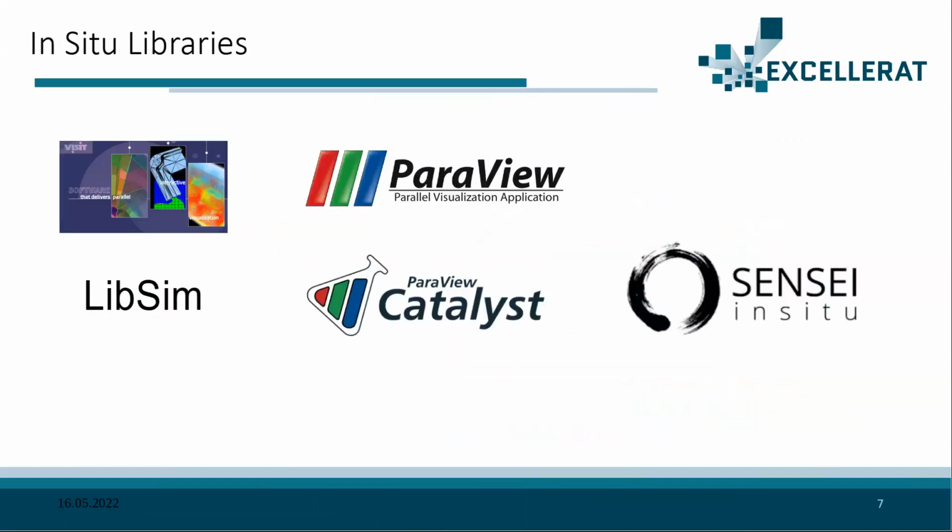And to do this, there are a couple of existing approaches. So as I mentioned, NEC already had the LibSim interface, which is a proprietary interface for the VisIt post-processing software. And the same applies to ParaView, another common post-processing software, which has its own proprietary interface. And we could have done something similar for Vistle and NEC to implement an interface, especially for Vistle in NEC. But we didn't want to go this route because it's not really scalable. It would force other simulation developers to basically put in the same amount of work to make their visualization software capable to run in situ with Vistle. And so we chose to do a more general approach.